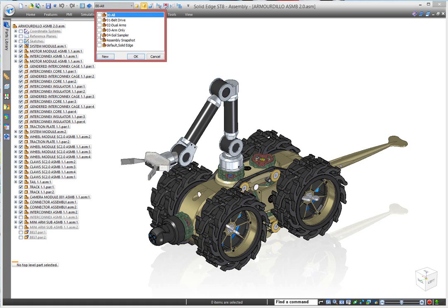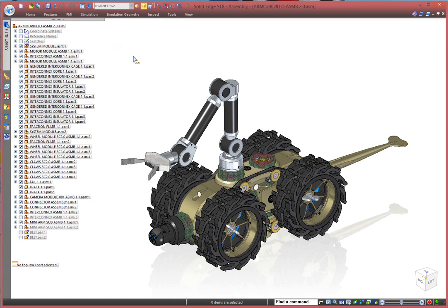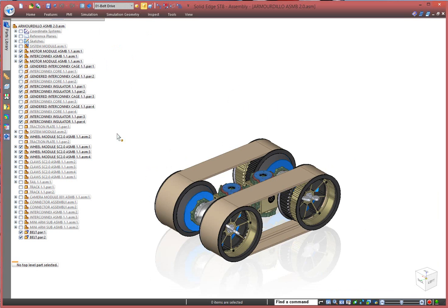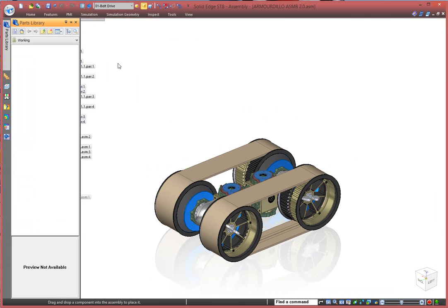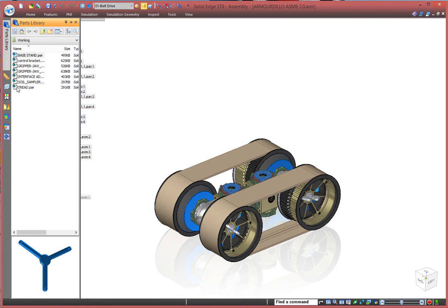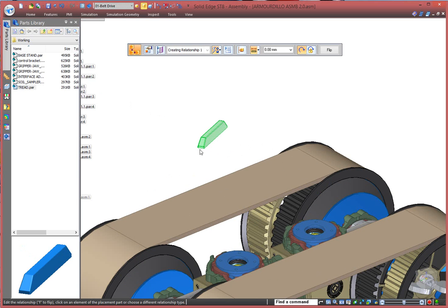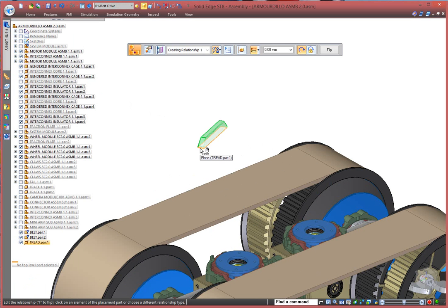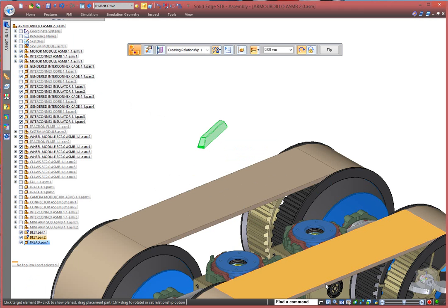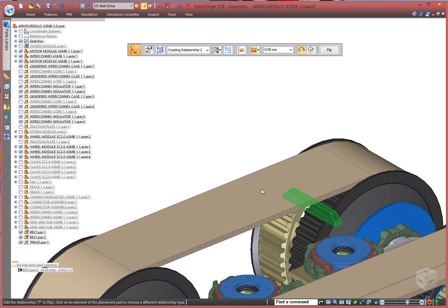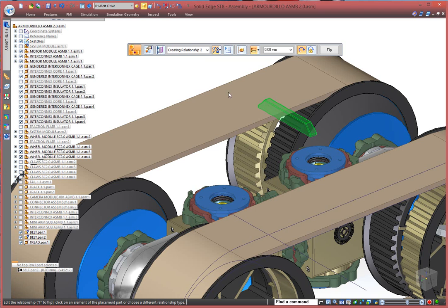Depending on the terrain, this robot may need a different kind of tread, so we can quickly change our focus to the area of the drive system. You can see the belts have already been added, but we also need to add a tread to the assembly. With this tread part we can use both the belt and an assembly sketch as our paths to follow along. Just applying a face-to-face relationship there, quite simple. We'll use the sketch next.